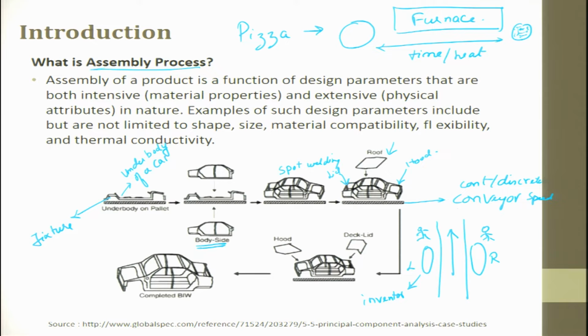And the beauty of an assembly line is that the cycle time for every process is tagged. And if one station stops its production, the entire line stops its production, because the conveyor cannot move to the next station with a defective part. If there is a defect which you could not rectify and it is allowed to move, all further operations on this defective car will not happen and the car will be exited out as defective or rework.